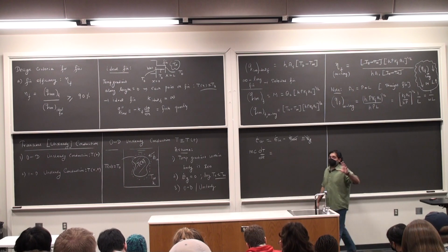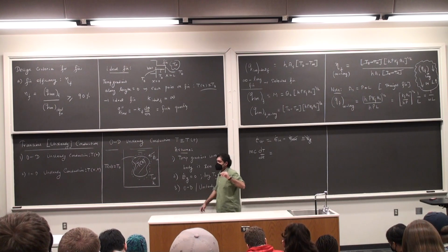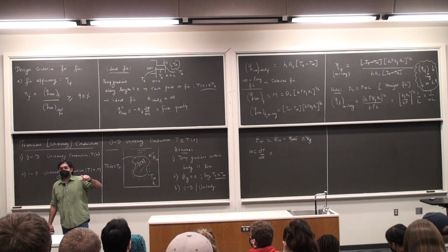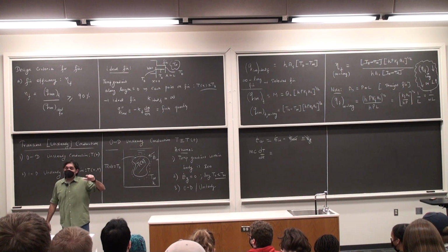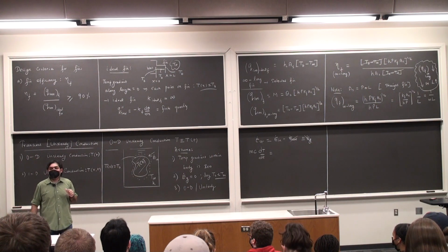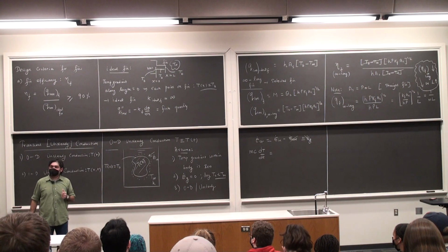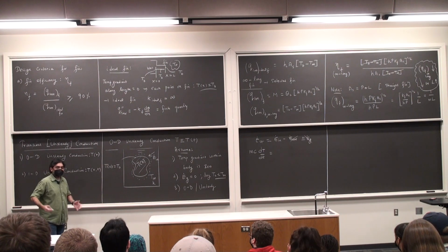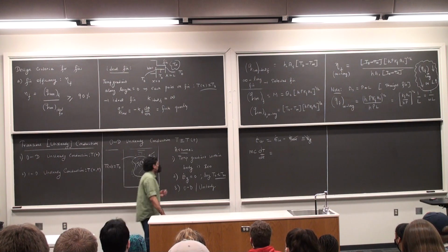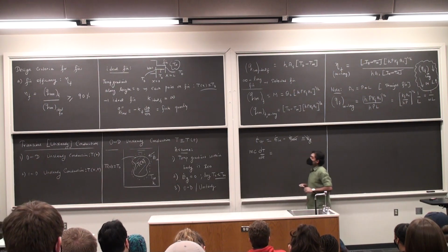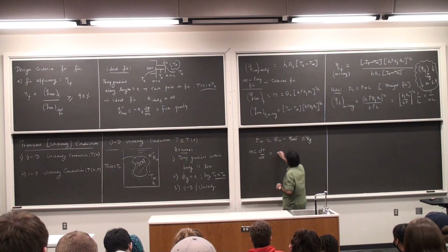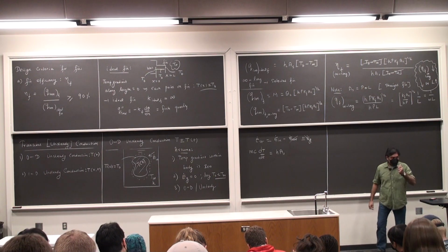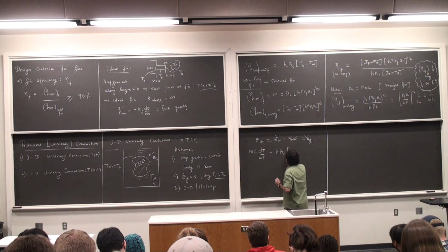One of you told me that in your practice midterm exam formula sheet, my convection formula is wrong. It's not wrong. I did not specifically tell you what the direction of heat transfer is. That is up to you, and that is up to the application. If the fluid is hotter than the body, heat comes from the fluid to the body. If the body is hotter than the fluid, vice versa. Okay? So E dot in is going to be h times A surface area, times the temperature difference, T infinity minus T of t.